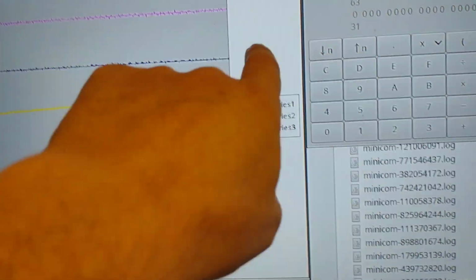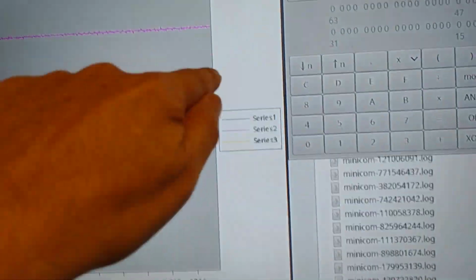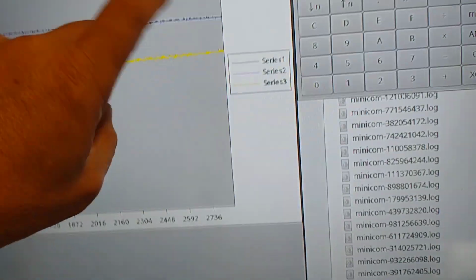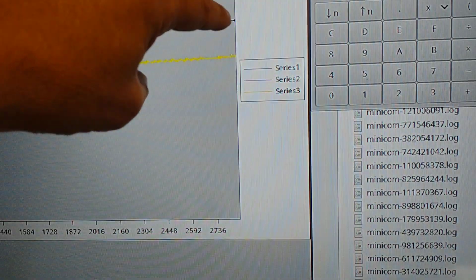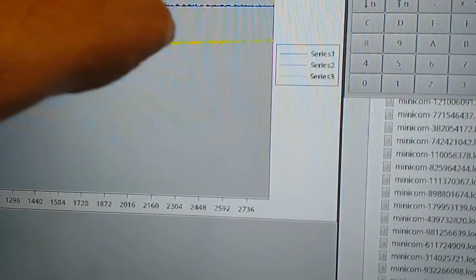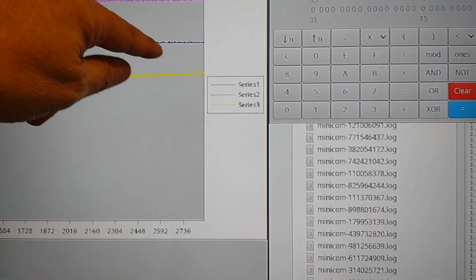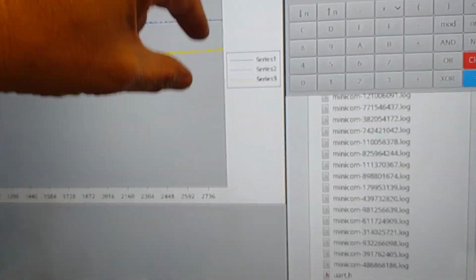So this one is essentially going to get left behind. Then this one will be low in the pack. So what you do then is switch your charger to that one and bring that one up to the average. And then presumably it'll change again. So you keep going until eventually all 3 of them are balanced.